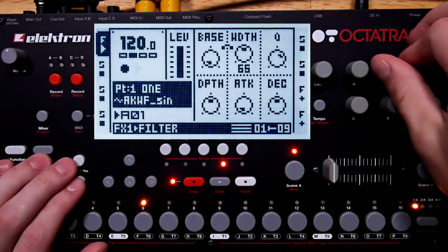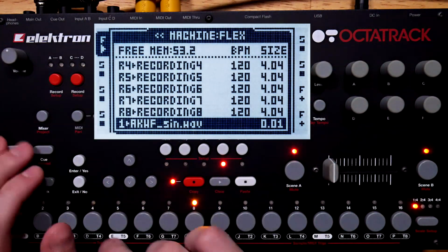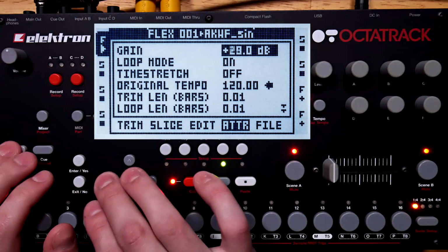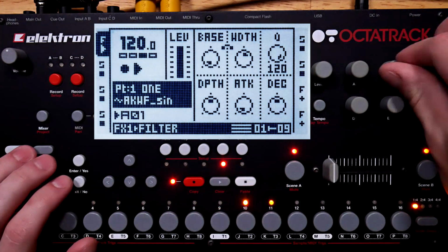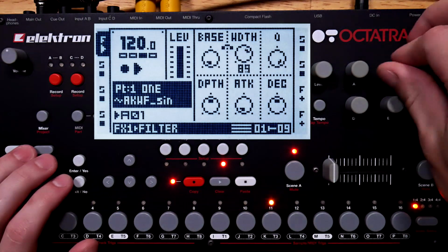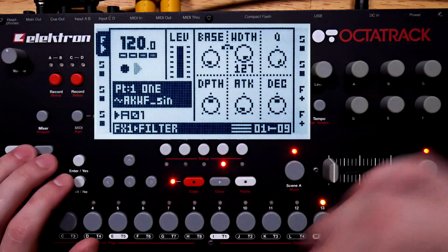The very high signal levels clipping the input of this filter are creating a lot of harmonic content for the filter to chew on. Since the source is so harmonically simple, once we remove some of that clipping, the interaction of the filter cutoff frequency and the Q becomes much more dynamic.